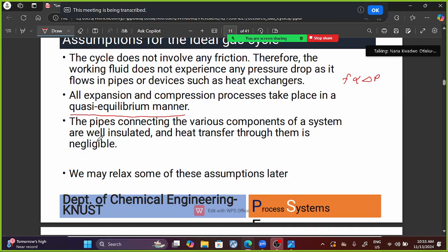So there's a point where we have heat being added to our system and removed from our system. Those are the only parts where we assume heat is being added or removed. At every other location, we assume that heat is not being removed. Once again, that's a very important point, because when we start looking at the different cycles, Otto, diesel, and Brayton, you will see graphs like this, with Q in and then Q out, and then this side here is going to be a constant entropy.